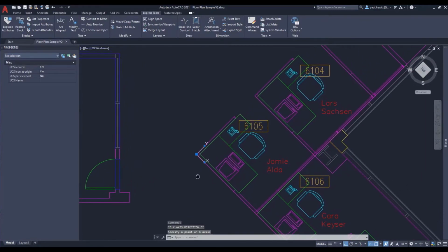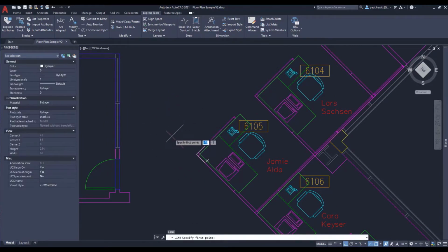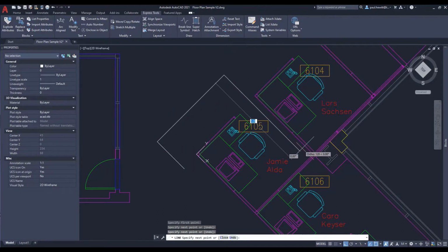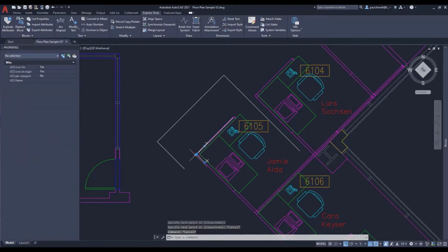Click on it and then select the Move grip to place it into the angled object. Once attached, click on the round end grip and rotate it about the Z-axis to align it with your object. Now you can quickly create your geometry in relation to your desired angled object.